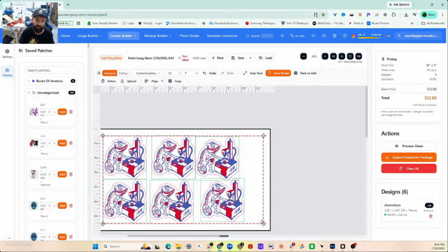I mean, you could, I guess, if you have a camera, lay it on top and line it up, but I would suggest print and cut because you can use it on any kind of laser in Lightburn, and you don't even need a camera at all. And it's very, very accurate if you know how to use it. If you don't know how, just message me and I will teach you how.